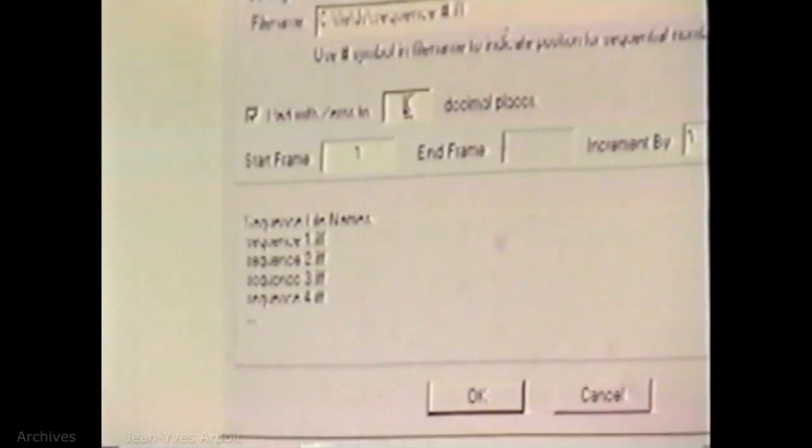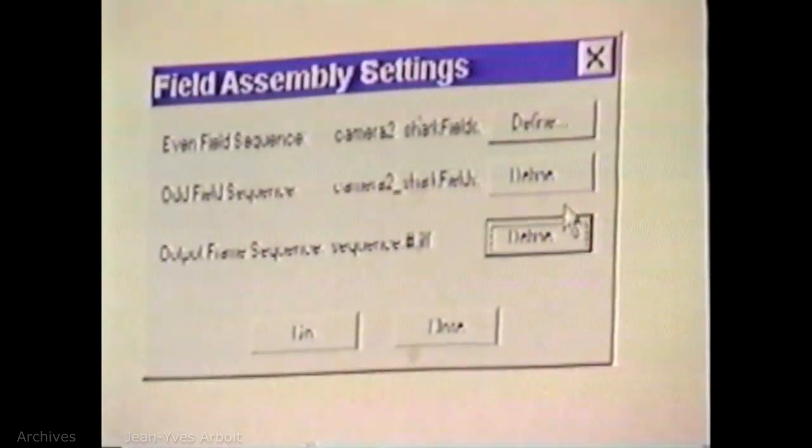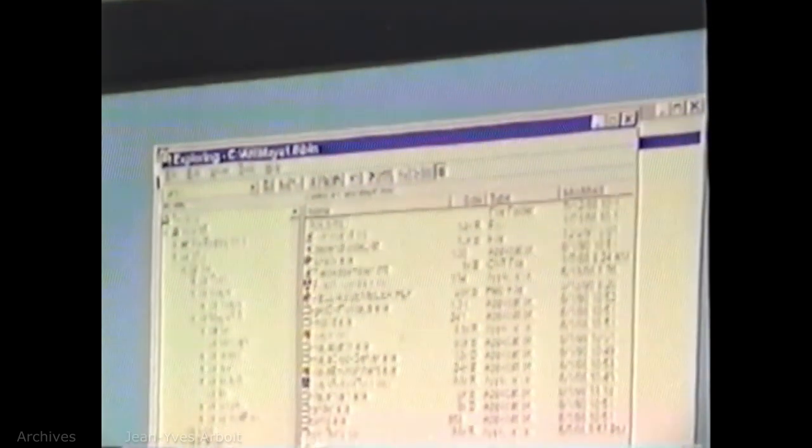especially for After Effects. So if somebody renders an NT and they need to go to After Effects and they say, this is the wrong order, I didn't set my environment variable, what do I do? You tell them, well, you can use this to switch that. And this also has padding. So there's a check mark right here. You have padding, switch that to 4. And you notice inside this box right here, it's changed the padding. So once again, this is an example of the output that you're going to get. Okay? So I've defined my even, my odd, and my output frame sequence. I hit go, converting frames, done. Okay? I finished converting. So it brings up this big old window.